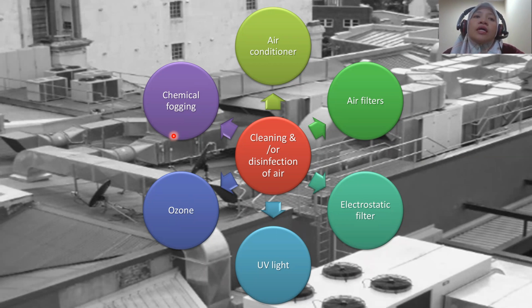Before fogging, food products and packaging materials should be removed from the room and the area vacated of all personnel for 2 hours. After fogging, all food contact surfaces should be rinsed with potable water or with water containing hypochlorite solution at about 200 ppm chlorine.